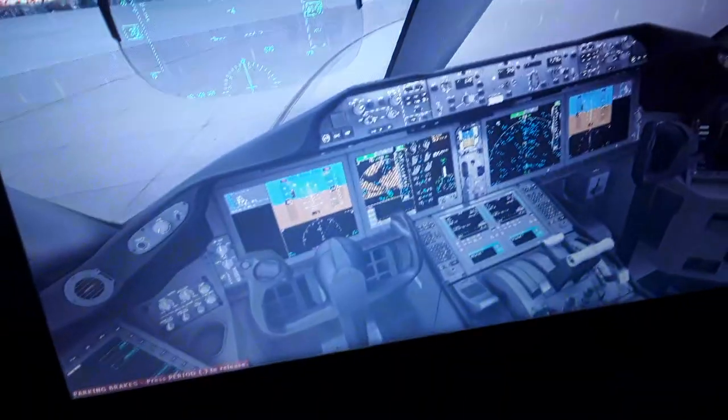We have also the VOR stations, the ADFs and the DMEs, the navigation aids, the navaids, also the waypoints which are horizontal and vertical navigation fixes and altitude and airspeed constraints. We're gonna select some waypoints from the flight management computer later when we create the flight plan. So you will see how we're gonna use the flight plan, the magenta or purple line. It's gonna connect all the waypoints one with another for this flight. So we're gonna have a route or a flight plan or a flight path for this aircraft.